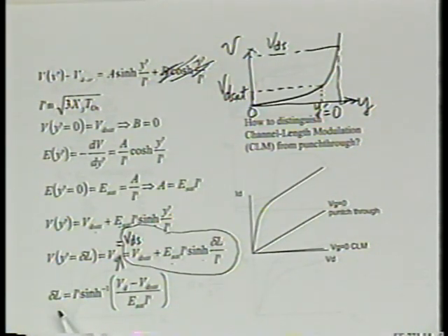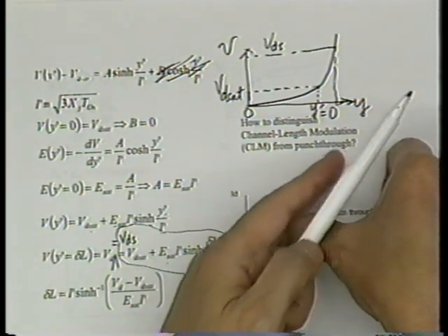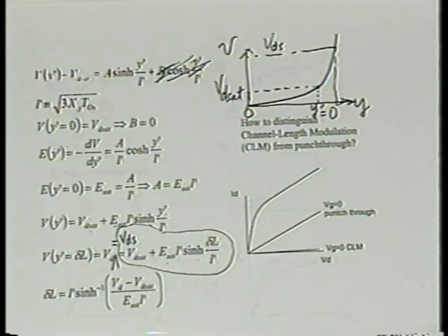Actually two kinds of things. One is decreasing the oxide thickness, and another is reducing the junction depth. Absolutely right. Decreasing junction depth, decreasing the oxide thickness. So here you see another reason we want to scale the oxide thickness, to scale the junction depths, right? If we don't do that, IV curve might look like that, right? This is very arbitrary hand drawing, of course, right? See what I'm talking about? Yes? All right? Okay.